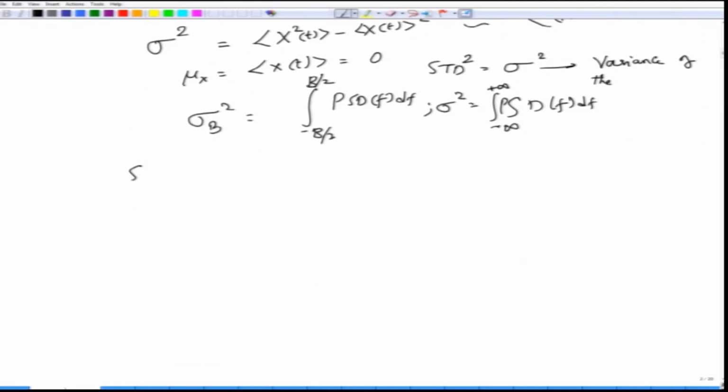Well, we define the signal to noise ratio as the average signal power to noise variance. Okay. Both measured with respect to, say, a 1 ohm resistor, that is to say you assume that the signal is actually dissipating some power in a resistor. For simplicity we take this resistor to be 1 ohm, and noise variance again is the power of the noise inside that 1 ohm resistor. Okay. This would be the total noise variance inside the bandwidth that you are looking at.